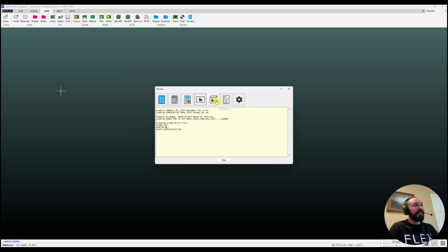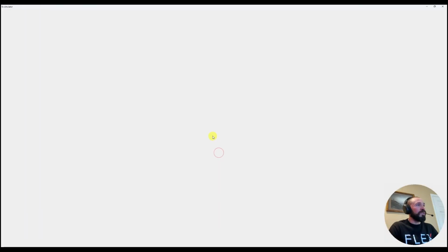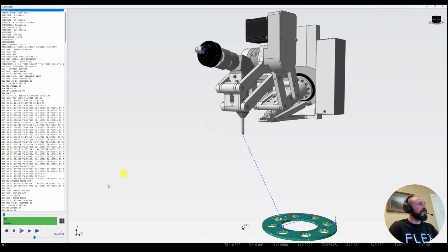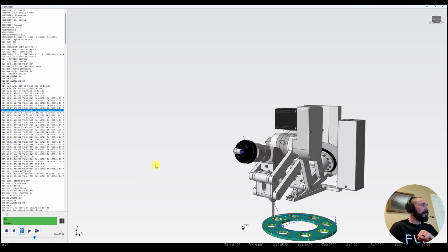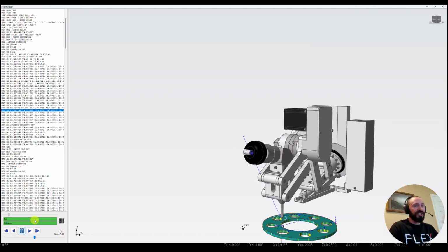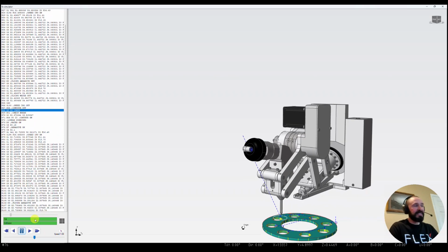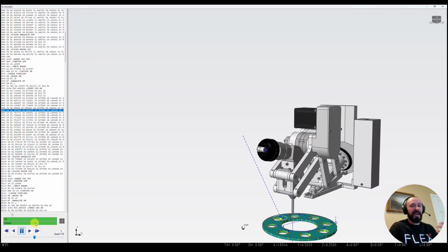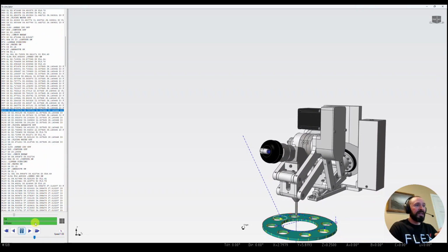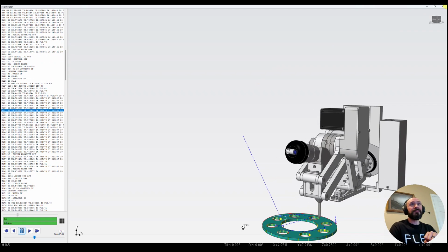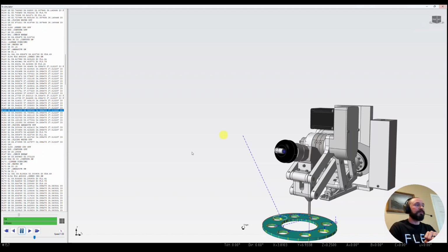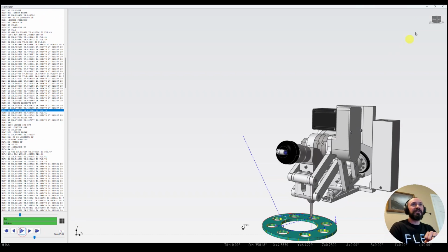I can actually do a 3D simulation, which is useful if you're doing taper angle compensation parts or cutting 3D geometries. And again, we can run through and do a full 3D sim, doing tilt checks to verify that our cutting head setup is valid, or collisions if we have clamps or other tools, or work holding fixtures modeled within our environment here. Whoops, let's go ahead and pause that and exit.